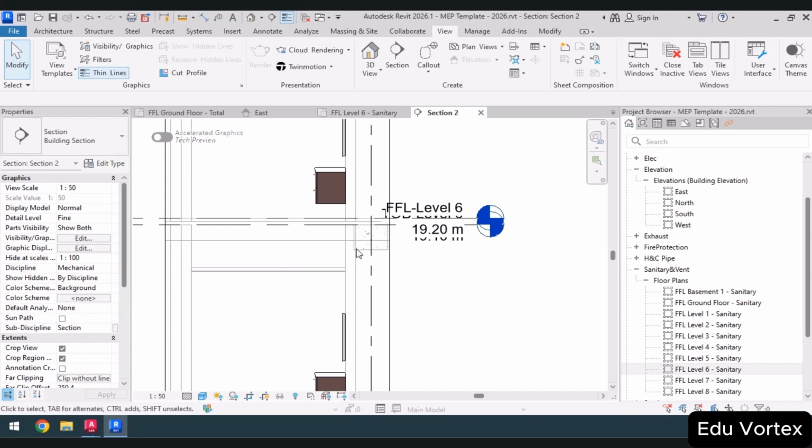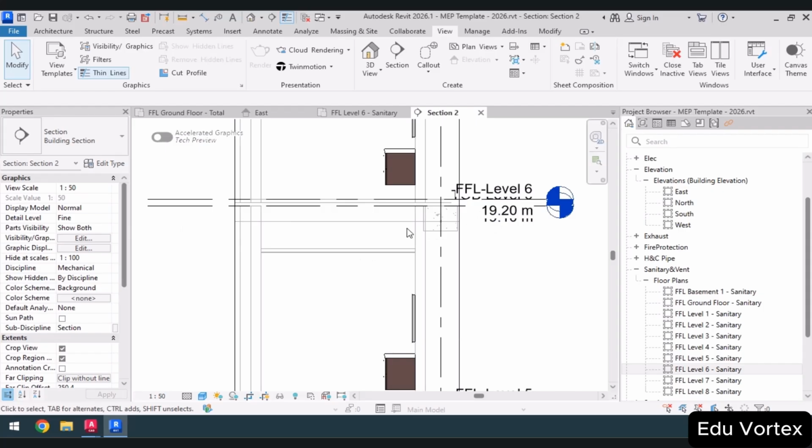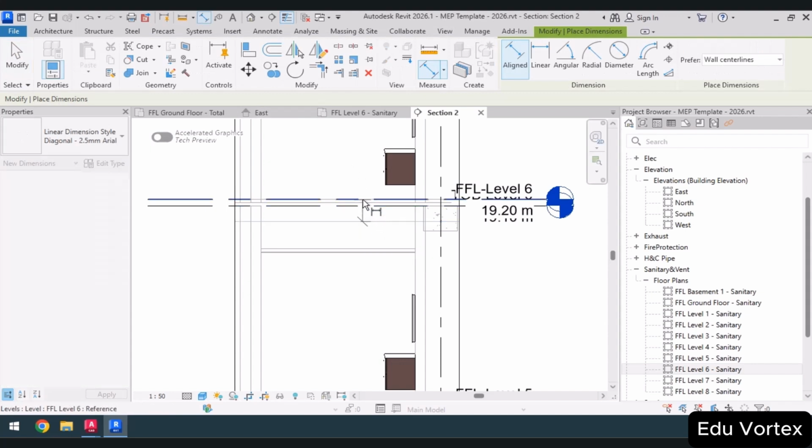So eventually, I need to consider the height of the beam that is the path of my pipe. For example, if I consider the wash basin, there is no beam in its path. Looking at the beam, it is located before the restroom space, so it does not limit me. Now I need to measure the height of my ceiling using the dimension tool. So clicking from here to a blank space gives me 35 centimeters.